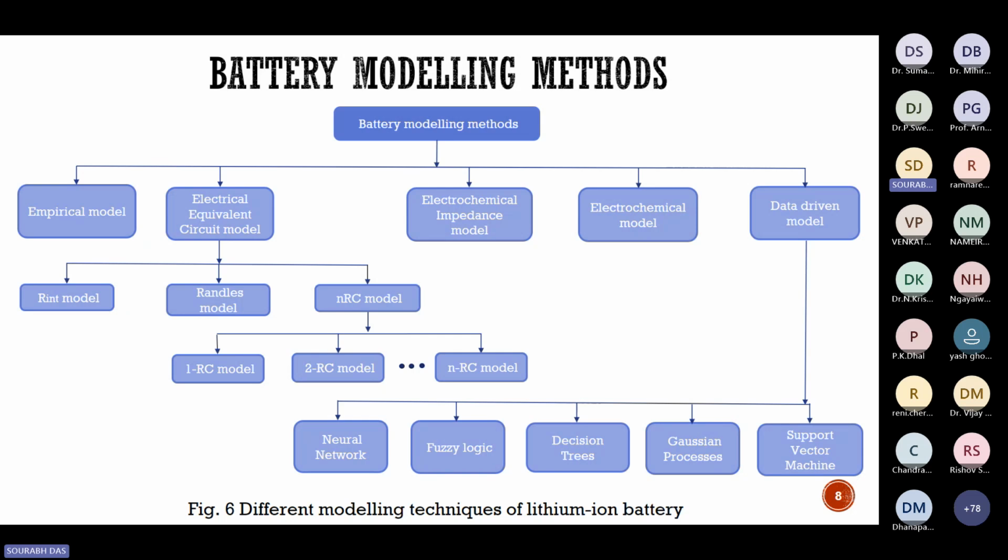Electrochemical models are mainly physics-based models. They can simulate the electrochemical processes in the battery. Here intercalation methods are used to design the model, and the microscopic and macroscopic views of the electrodes and the electrolytes are used.